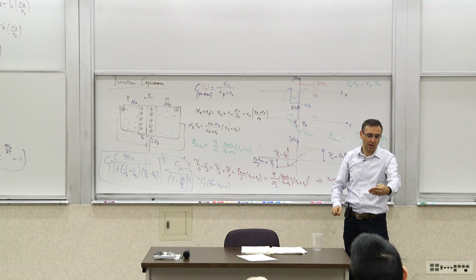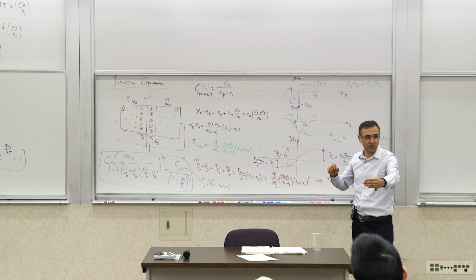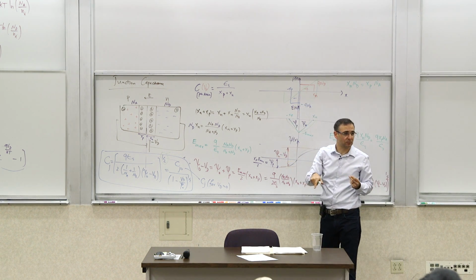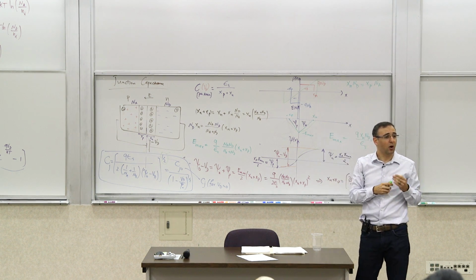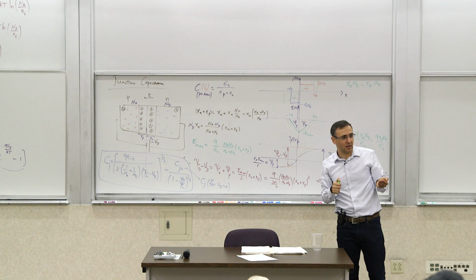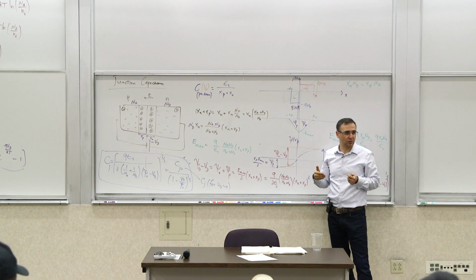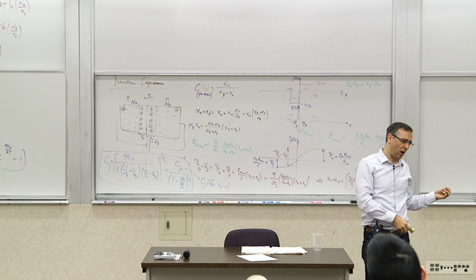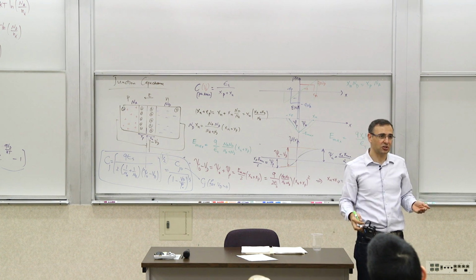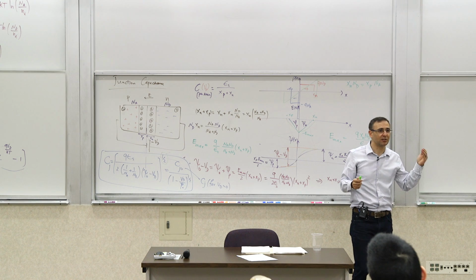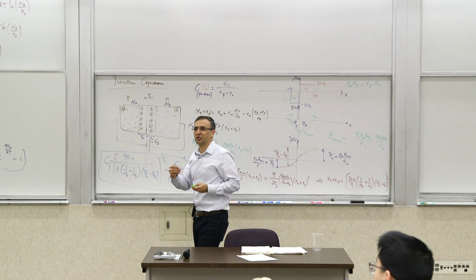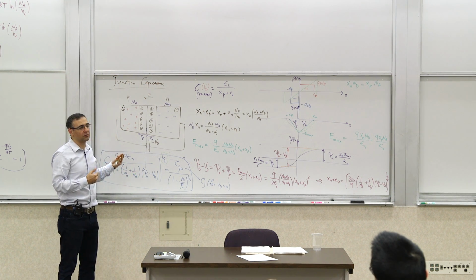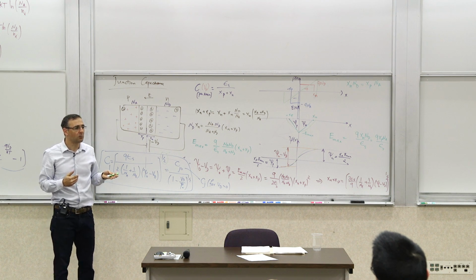So you can actually create a profile by smashing some deeper ones at a higher energy and the lower energy ones. So that's why you can never actually make this exact thing. You can make things that are close to it, but you can also create any profile you want, or some approximation of any profile that you want, by controlling these levels of implantations, how many you have. At some point, it may become impractical. Say, well, I want this, yes, you can do it with 20 different implantations. If you have the money to pay for it and the time to wait, yes, sure. So there's a trade-off between the practicality of the number of these things that you want to do and the accuracy that you want to achieve, right? But those are the ways.